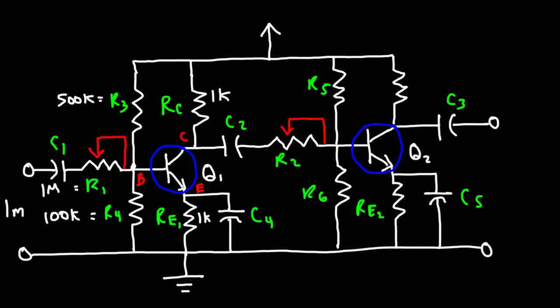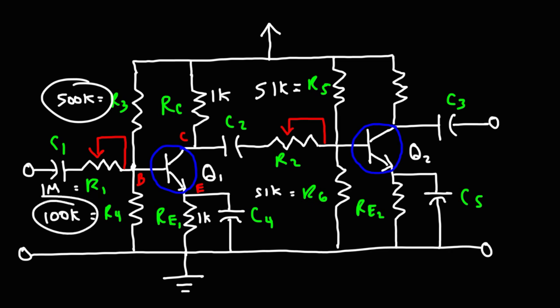So because we're dealing with higher voltages in the second stage of this circuit, we're going to make R5 lower. I'm going to make it 47K. You could make it 50K if you want to, but you usually don't find a 50 kilo ohm resistor. Chances are you'll find a 51 kilo ohm resistor. And for this, chances are this will be a 510 kilo ohm resistor. Now I'm going to make R5 equal to R6. Here I didn't do that because it really wasn't necessary, because the input voltage here will be very, very low.